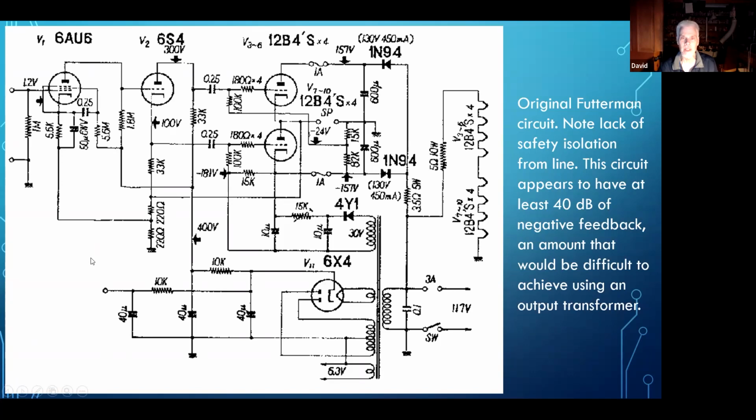If you were designing a modern day op amp, this is the kind of ideal way that you would go about it. You want that dominant pole so that you can get very, very high stability. And that's the key to being able to apply a lot of negative feedback: you have to have that stability, and you have to have that single dominant pole and no other screwy things in the circuit to affect phase shift anywhere near where that dominant pole is working. And if you study the circuit with that in mind, you can see that, hey, this is actually pretty good.